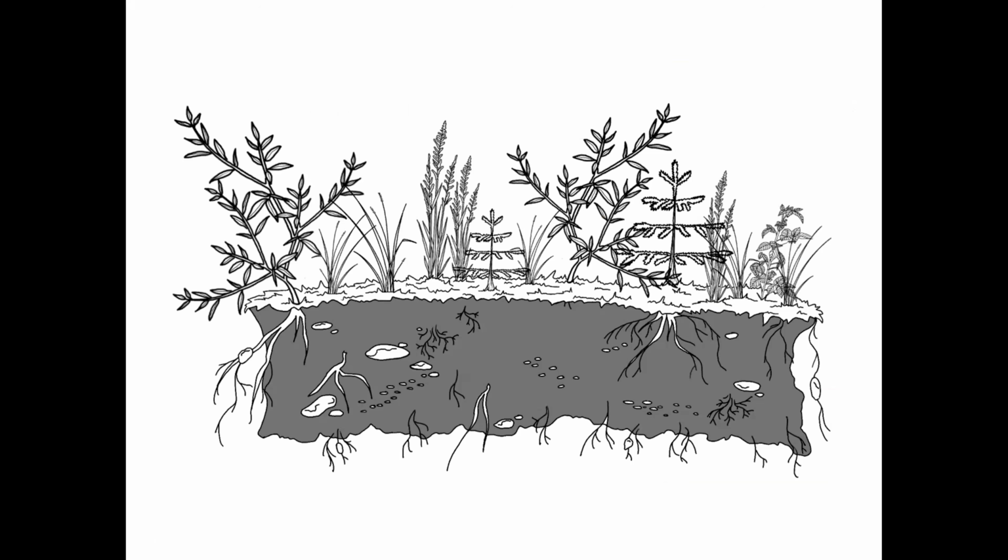So this quick illustration is just to drive home, again, the point of harvesting the veg mat and including at least 6 inches of root mass and soil when doing the harvesting. On many sites, it's appropriate to have your mat include woody and herbaceous plants, but this may vary depending on your site and location.